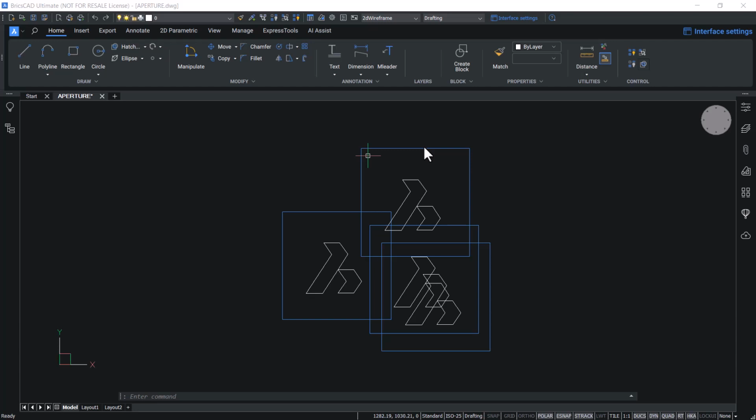A large aperture cursor makes it easier for you to hover over geometric features, but the program may find too many matching entity snap points. In this case, you can see that there are too many matching points within the aperture. A smaller one may be more difficult for you to position over the geometry, but is more precise at snapping to geometric features.